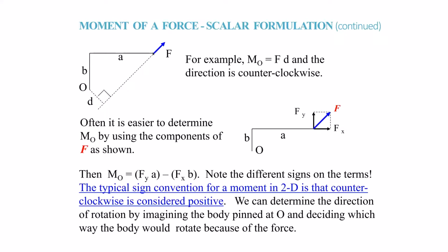You have some choices here. You take this line of force and draw a straight line all the way through. If you can come up with the length, which you could, and it might be easier to do this a little differently, but say you come up with the length of this distance here, the moment would be just this distance times the magnitude of this force.